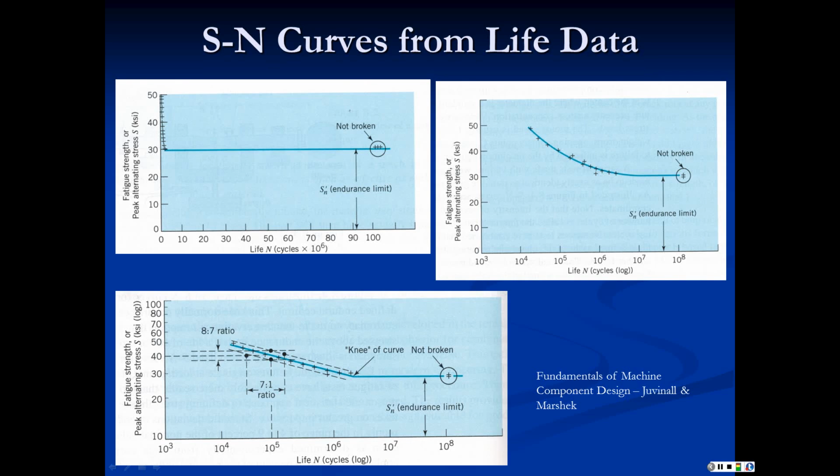Endurance limit is the first parameter that goes into estimating the allowable stress in fatigue. And then we can modify the allowable stress to allow for surface finish and other things, but this is the stress below which you have infinite life. So you'll hear this called the endurance limit or the fatigue limit, and may even be called the fatigue strength, although that's not strictly true or accurate.